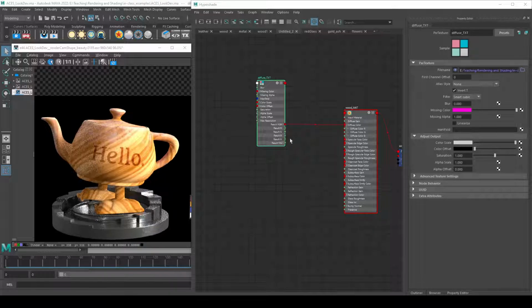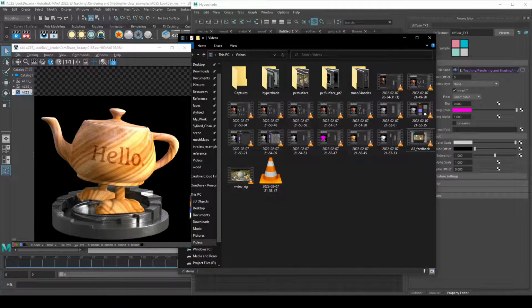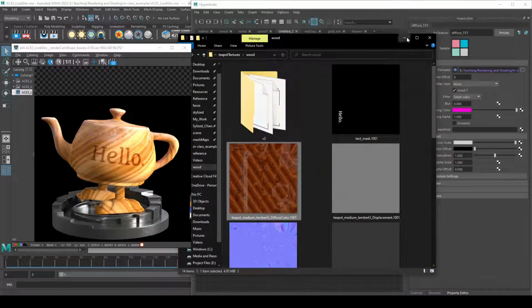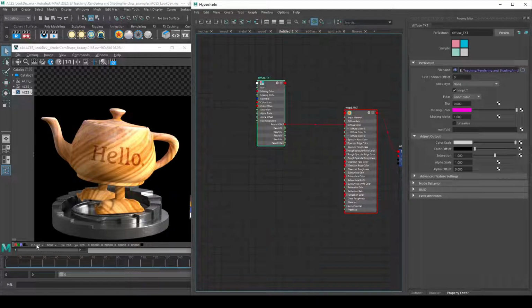Okay, so I loaded in my diffuse color map, and you'll notice, maybe you don't, but it's not quite right. So if I come back to my materials and take a look at this, you'll notice those colors don't quite look correct. And that's because by default, I'm working in a linear sRGB color space. I'm not talking about any other color spaces right now, not ACES or Filmic Blender or anything else like that. This is just the default RenderMan linear sRGB. And so if you haven't thought about color spaces before and you don't really know much about them, you shouldn't really have to worry about it. So don't think too much about it.